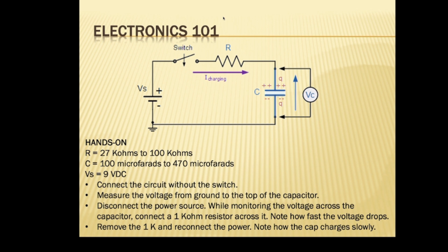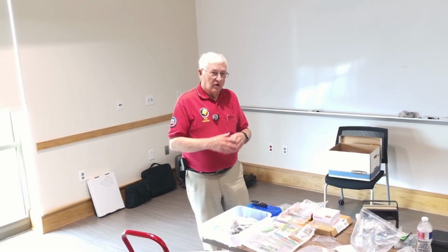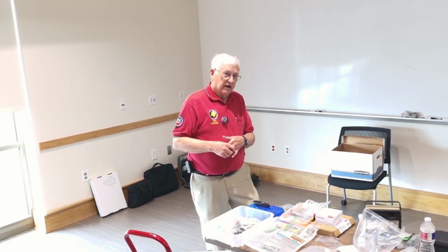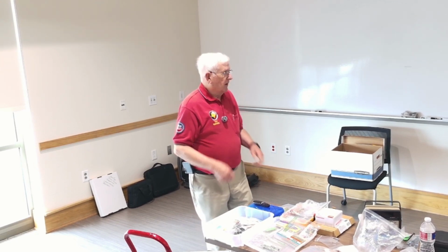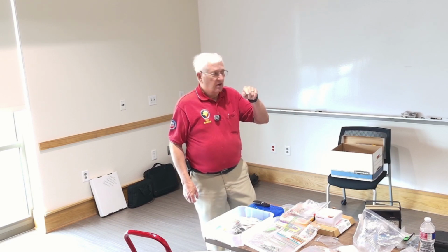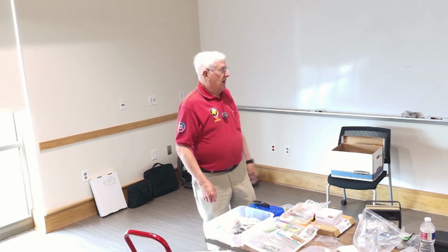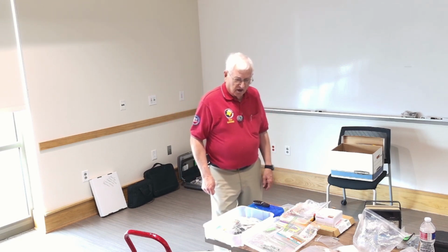Does the voltage matter? Yes. The capacitor will be rated at so many volts. Anything we have here will be rated above the 9 volts we're using. But if we were in a real circuit where we might have 50 or 75 volts, we'd have to be really aware of that. Yes, we really would. Now, the electrolytics, remember they have the little stripe on them with the minus? So be sure to observe the minus and the plus on the capacitors. Make sure the minus of the capacitor goes to the minus of the battery.